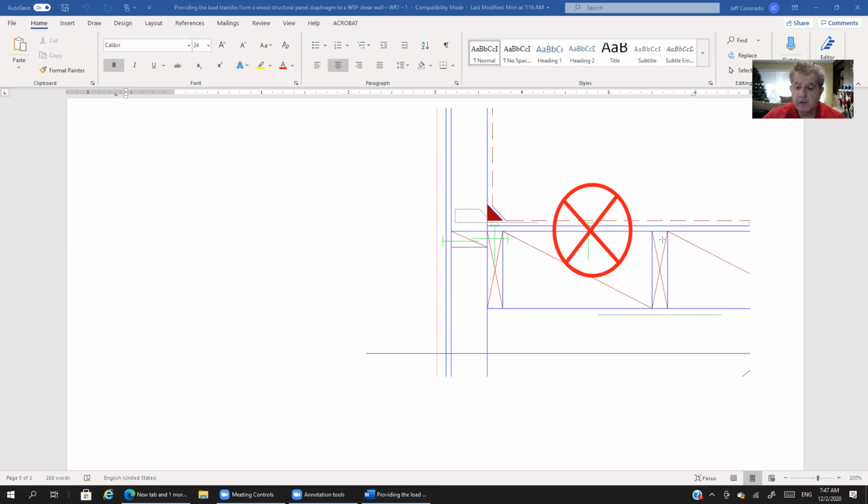What that means for us in structural engineering is that's how we represent a force going into the page. Think of it as an arrow. We're seeing the butt end of an arrow. So it represents a force going into the page. So that's the diaphragm force that we have here that we need to resist with this nailing assembly that we have here.